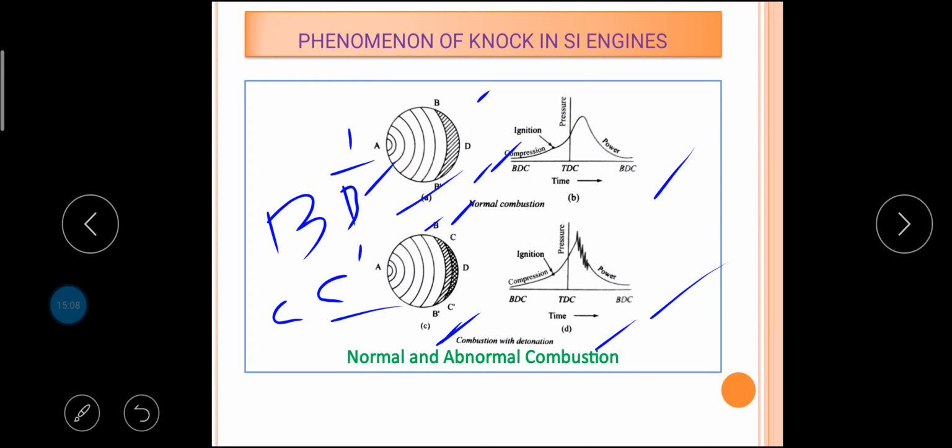In summary, when autoignition occurs, two different types of vibration may be produced. In one case, a large amount of mixture may autoignite, giving rise to a very rapid increase in pressure throughout the combustion chamber, and there will be a direct blow on the engine structure. The human ear can detect the resulting thudding sound and consequent noise from free vibrations of the engine parts. In the other case, large pressure differences may exist in the combustion chamber, and the resulting gas vibrations can force the walls of the chamber to vibrate at the same frequency as the gas. An audible sound may be evident.